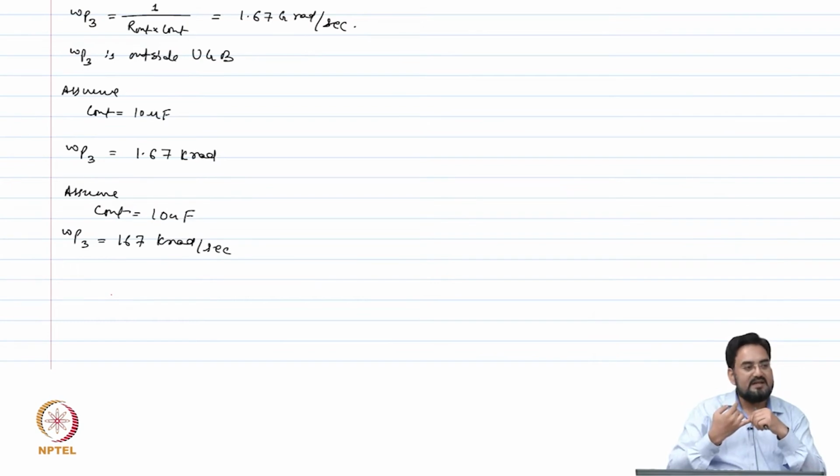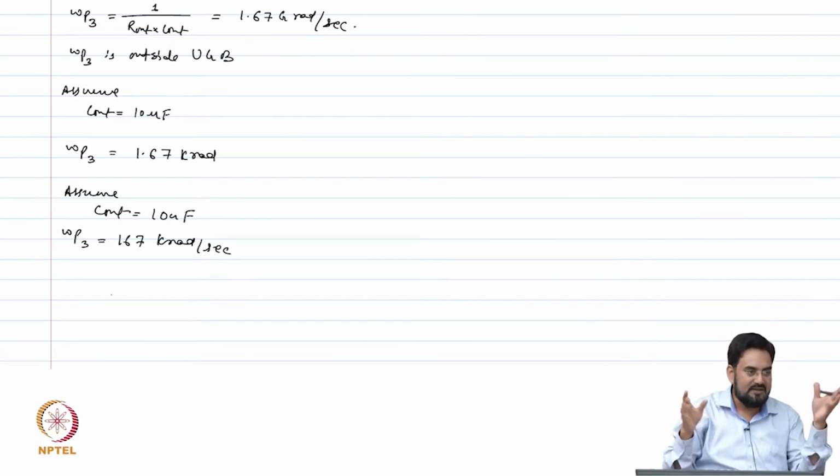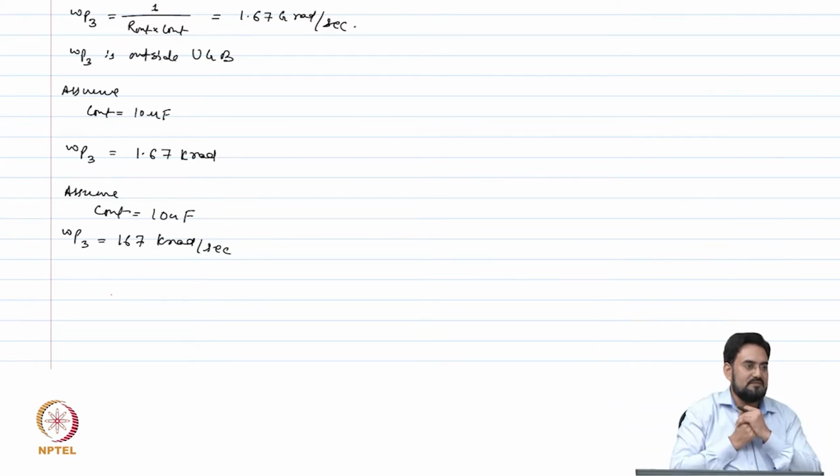There could be a case where your system is drawing a fixed load, let us say an on-off system, which is either drawing no load, when it is turned off, in which case you do not need to regulate the supply at all, or, when turning on, it will only draw let us say 10 milliamp current. In that case, whether you require a compensation or not will be determined by the C out. But if your load is variable, let us say 0 load to 10 milliamp.